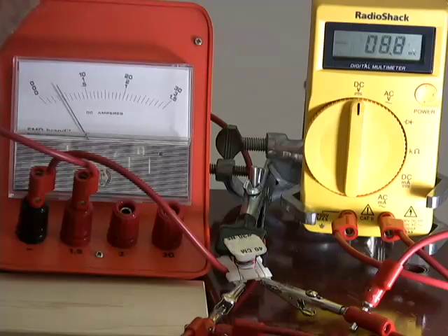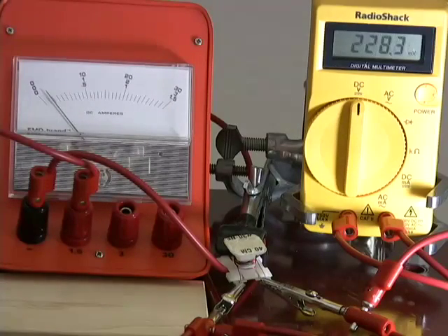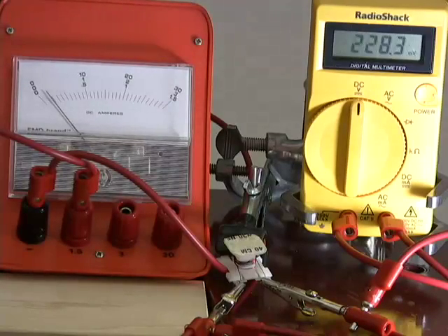Okay, there I have turned on, and I'm going to adjust the current, say there. Alright, now look at the shadow of the pointer. That is where you take the reading. Alright, measure the ammeter reading and the voltmeter reading. That's your V and I. This is your current values. That is your potential difference V values. Measure that. I'm going to change the current value.